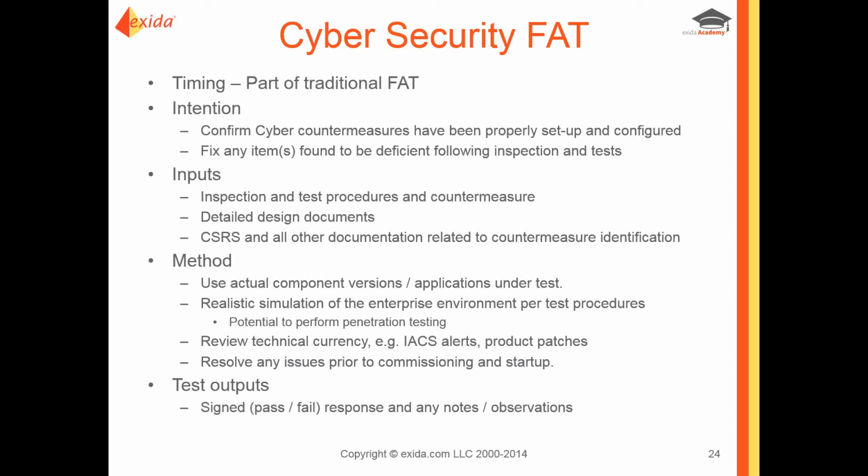The inputs to an FAT are pretty much the same as the regular FAT. You need your inspection and test procedures. You need your detailed design documents to check against. And in the safety world, you'd have a safety requirements spec that you want to check things against. Here, you should have a cybersecurity requirements spec to be able to check against.